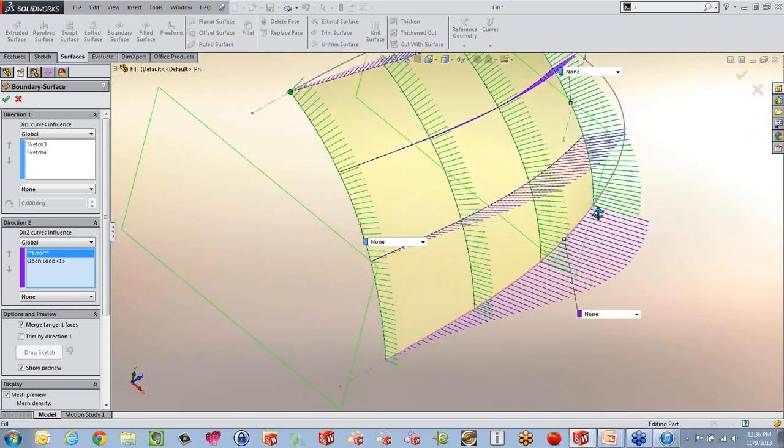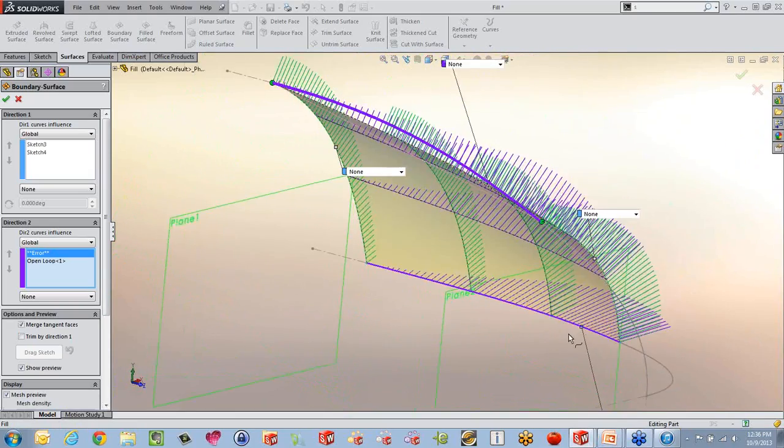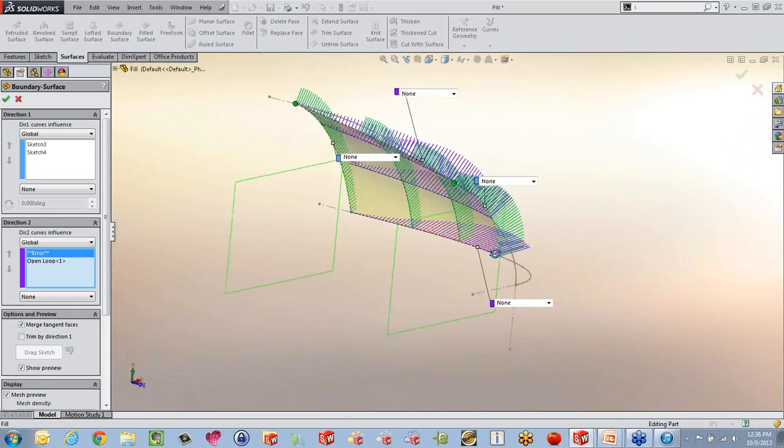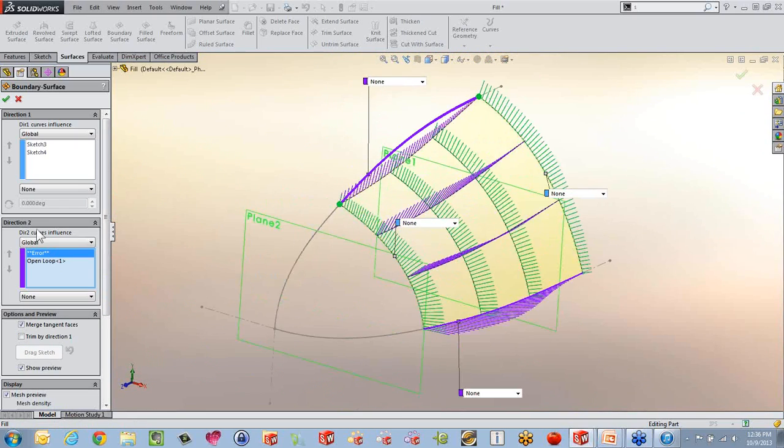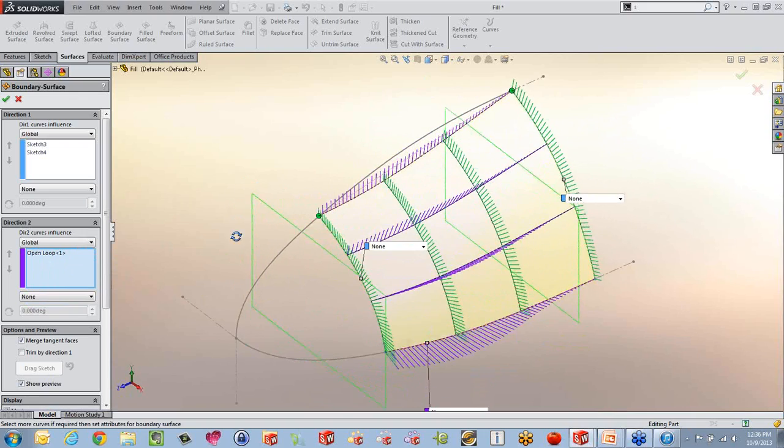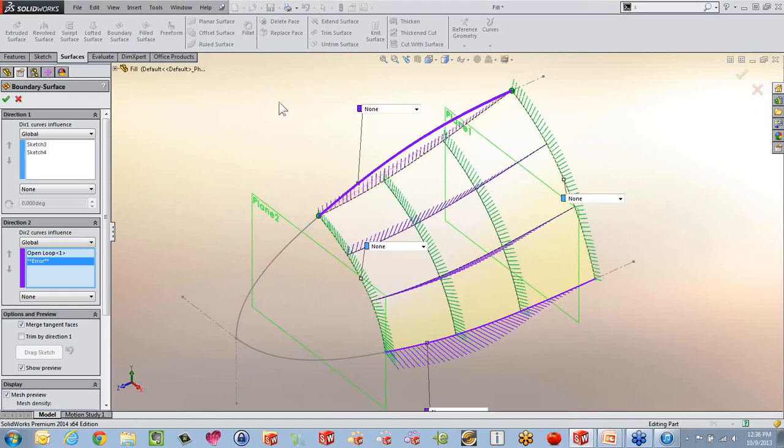So that's how boundary surfaces really work, it pulls it out down to the edge there. It's interesting, the top one is not happy. All right, look at that, right? Right click, selection manager, select the edge, pull it back here, see if it can do it. No, there's something going on with that. But that's the difference between the boundary surfaces that we have here.